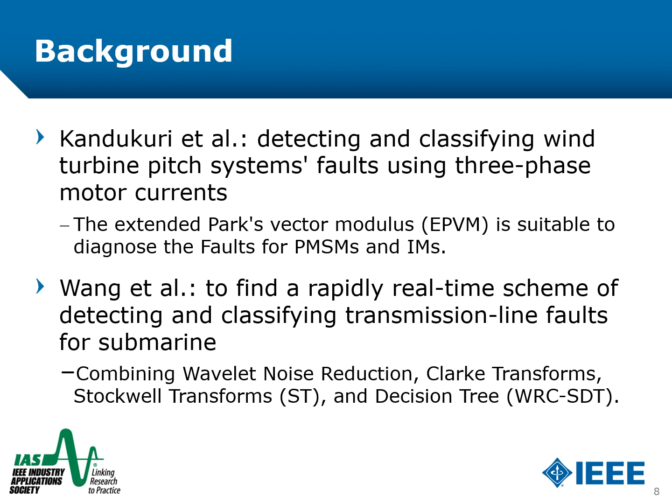To find a rapid real-time scheme of detecting and classifying transmission line faults for submarines, Professor Wang proposed a method to combine wavelet noise reduction, Clarke transforms, Stockwell transforms, and decision tree.